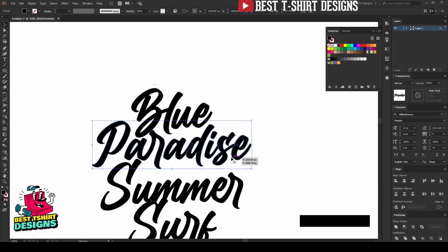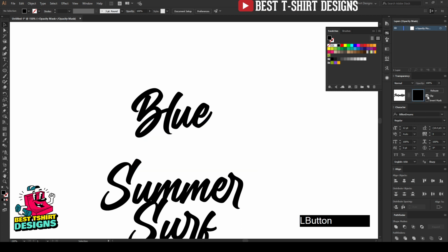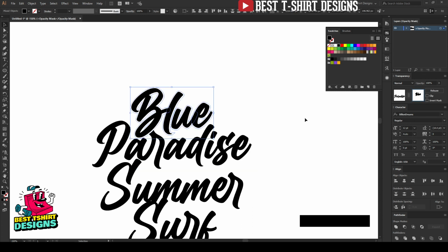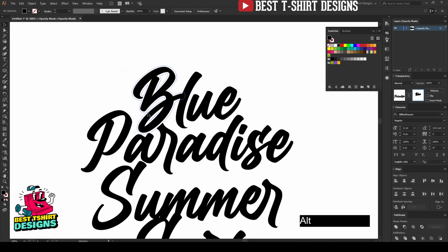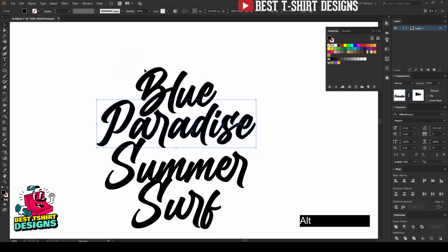I'm selecting this paradise text. I'm opening the transparency for it and pressing Ctrl F. Ctrl F will paste it in front, that means in the exact same place where it was, but inside the transparency. So that is how it looks, this cutout effect. I hope you know this if you are following my channel. So that is fine. Let's make them a group.